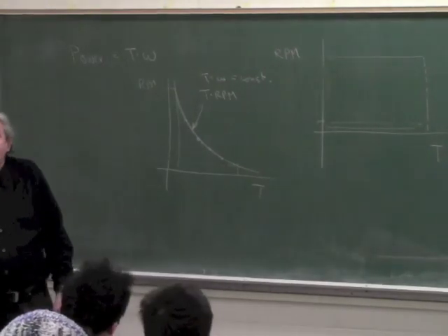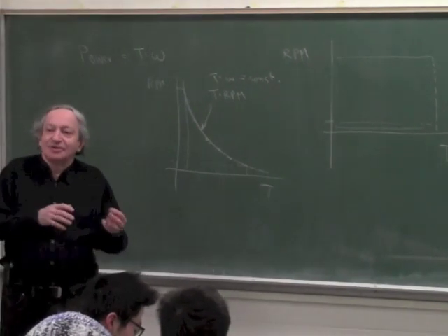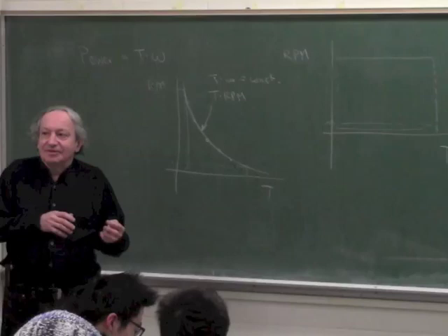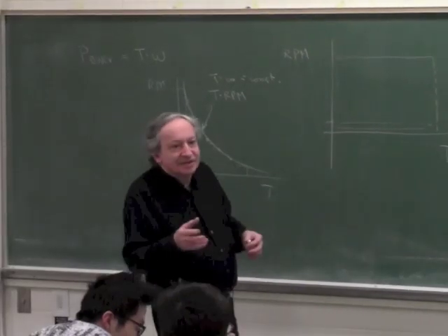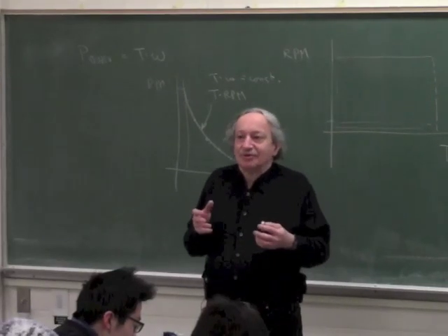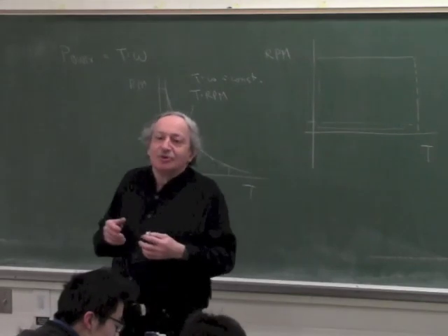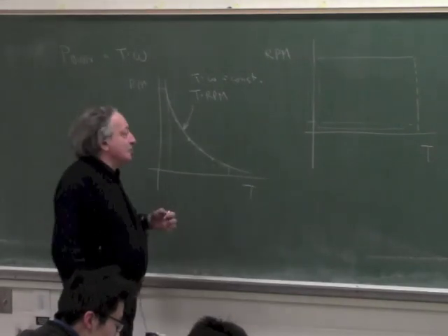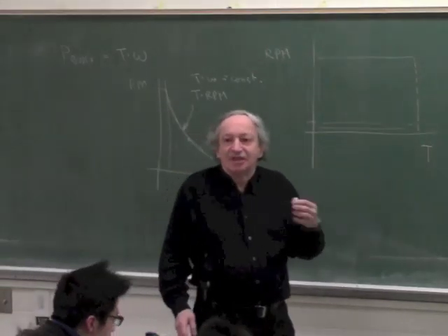Many things have gearboxes just to match the load to the motor. Because to make the lightest car or the lightest hand drill, you want to use the maximum power of the motor, and to do that you have to match the load to the characteristics of the motor, typically by using a gear.